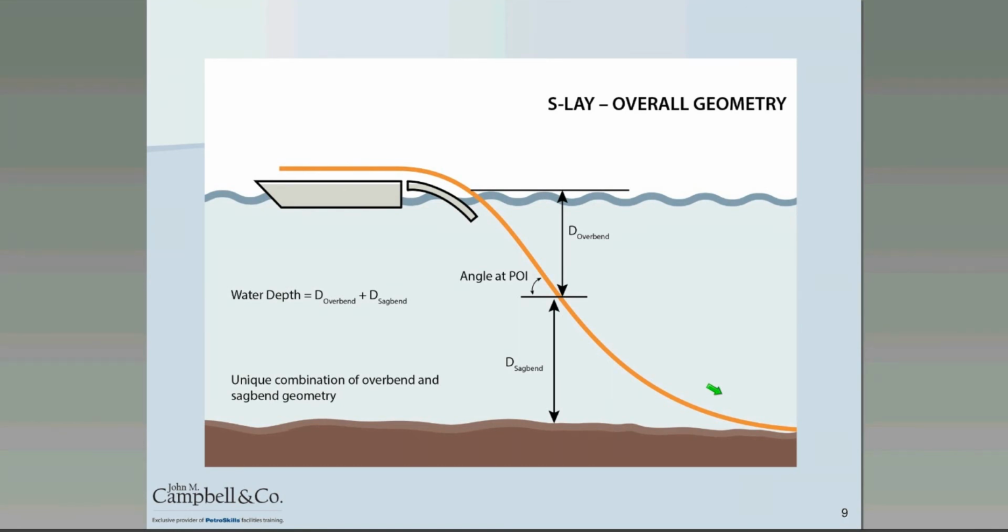There is some guidance in some of the industry documents, like from Det Norske Veritas. But all in all, this is a company decision, and most companies end up about in the 80%, maybe as high as 85% in the overbend, and 75% to 80% of the specified minimum yield strength in the sag bend. Those are very, very common numbers, and I've seen them used repeatedly for the last 4 decades.